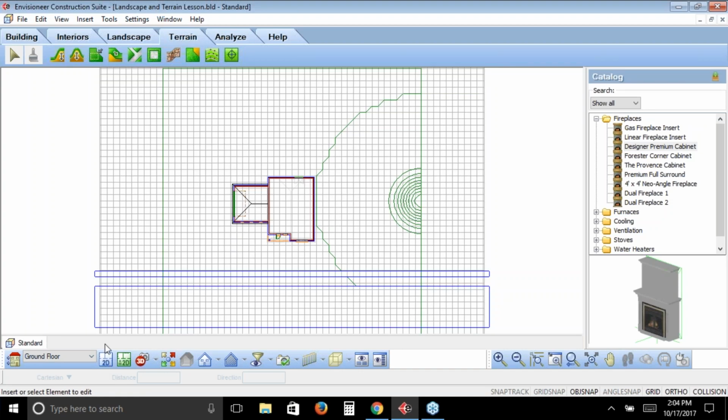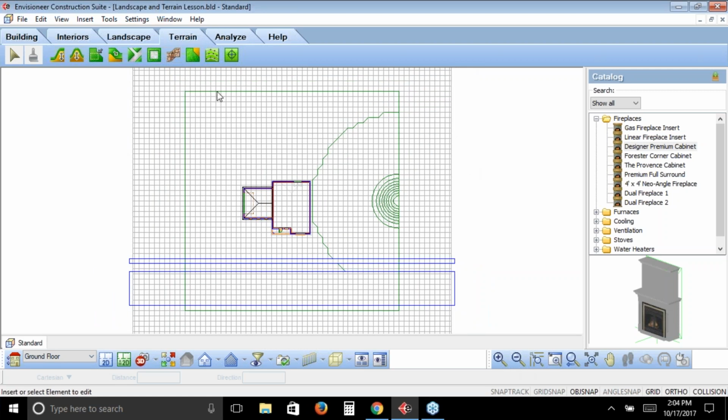When you're working on your terrain, you're altering the green bounding box that you see around the screen. I'm just going to highlight that for us. If you can't see it very well because of my grid, I'll just highlight that green line that's going around. That's my terrain. That's the extent of the terrain out on my 3D view. So when I'm putting in any kind of different topography for the site, it's going to start and end at that green bounding box as well.